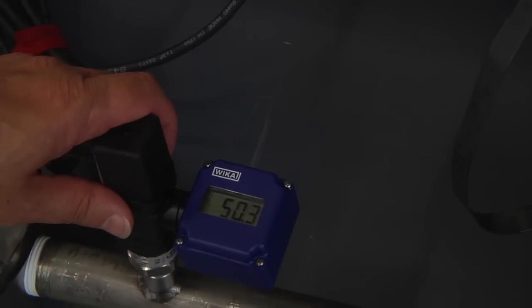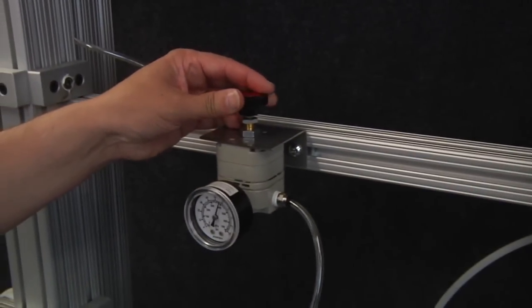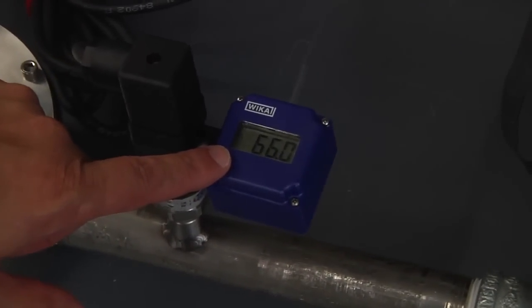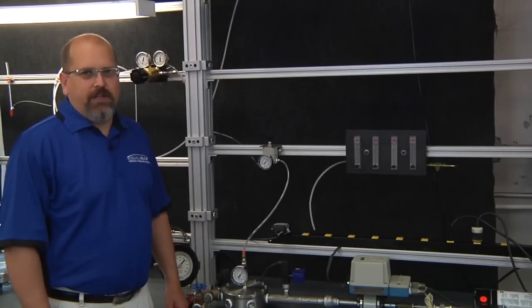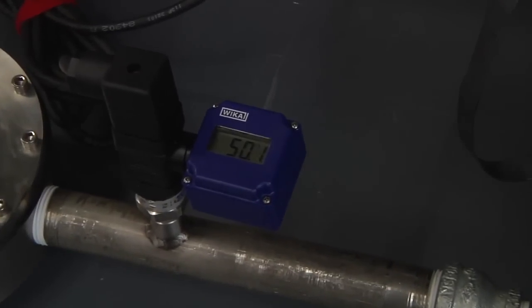And now to show the repeatability, I'm going to adjust the pilot pressure on the Equilibar back pressure regulator to get something more like 65 psi on the pump curve. That's going to give us a much lower flow rate. So I'll run this pressure up to about 65. And what we'll see is when we have 65 psi on the output of the pump, that the flow meter is at a much lower value. What's important is the repeatability of the flow control we can achieve. When I reduce the pressure back to 50 psi, the flow in the system comes right back to 4 gallons per minute through the flow meter.